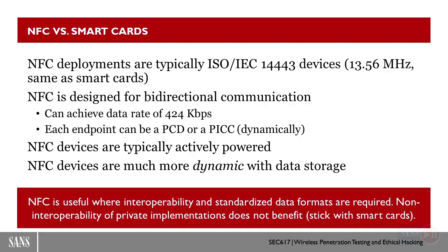They are typically ISO 14443 compliant devices acting as cards and/or PCD with bidirectional communication for up to 424 kilobaud per transaction. And we are potentially changing direction for that data transmission because it is typically one way. But if we change those roles, we can then have the data flow the other way. With these devices, unlike our hotel key cards, these are not powered. They are pulling energy from the read itself in the inductive coupling.